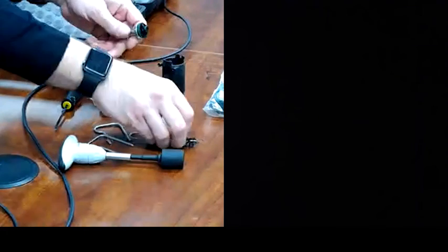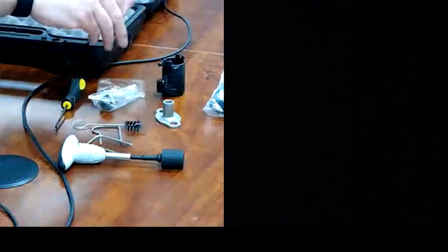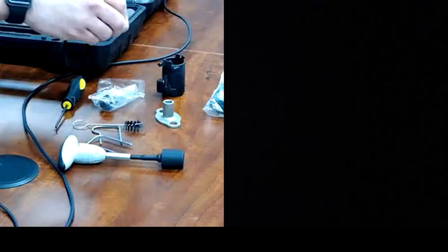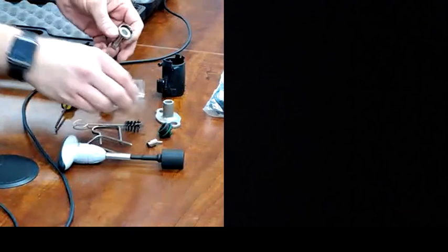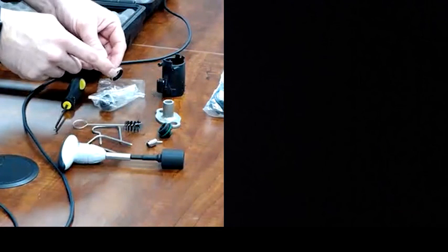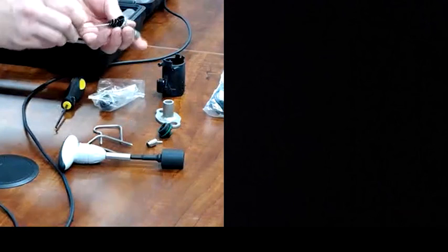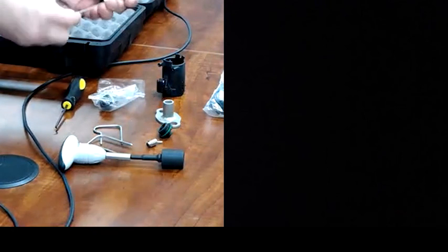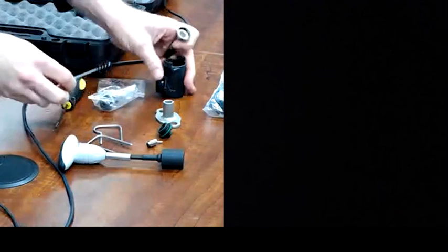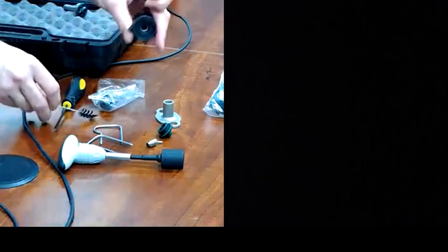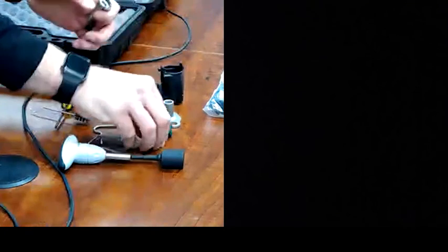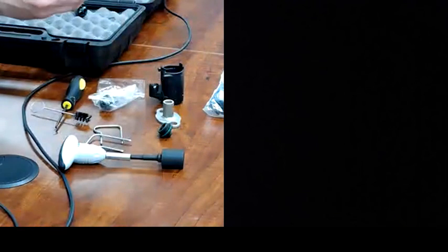The other thing I can do here is it does have a cleaning brush along with the kit. So we think about our end of year maintenance. This is a good place that if we have a poppet or a solenoid that's stuck, we can take our brush in there and give it a good clean out, and then also make sure there's no scoring in here. This shouldn't move either, but just to make sure if any debris does get in there that we get it cleaned out.